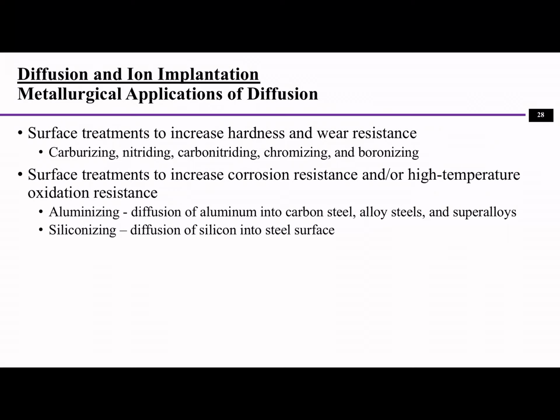So for surface treatments that can increase the hardness and also wear resistance, when we are using diffusion processes, it includes carburizing, nitriding, carbonitriding, chromizing, and boronizing.